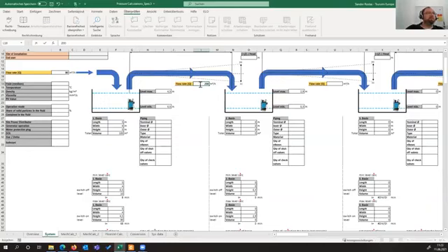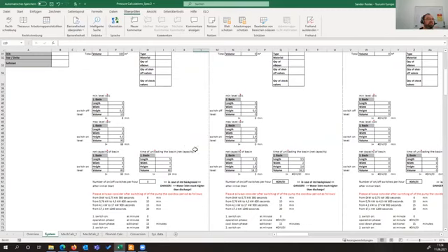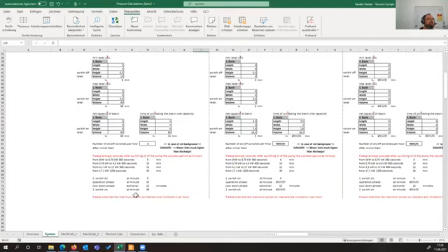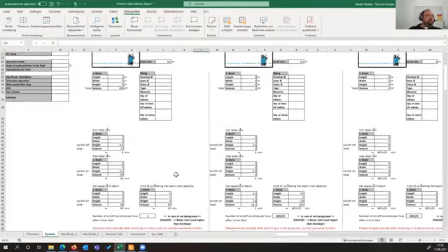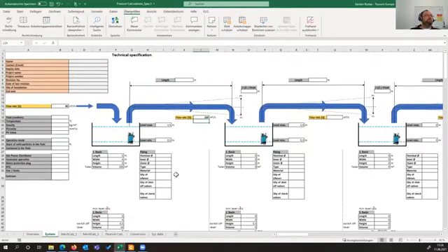If the customer requires 200 cubic meter per hour, of course, this will not really work because the switch on and switch off numbers after the initial start are already three. That means 4 times the pump will switch off and switch on within 39 minutes. And this is, from today's point of view, still prohibited. So let's continue.